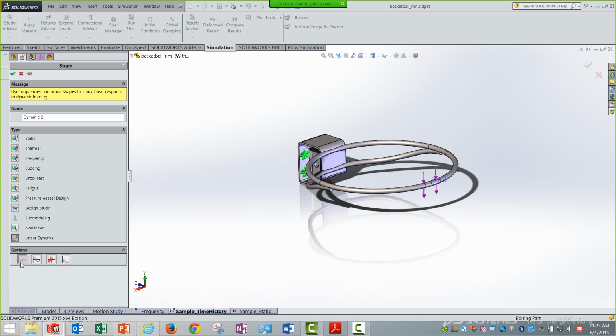Typically, nonlinear dynamic is a bit slower and takes more time to solve. But obviously it is more accurate, well, I would not say accurate, but it is more comprehensive than modal dynamic analysis. But for all practical purposes, people use this particular method of modal superposition, wherein we are doing frequency analysis first. Now, looking at linear dynamic, we have these different options.